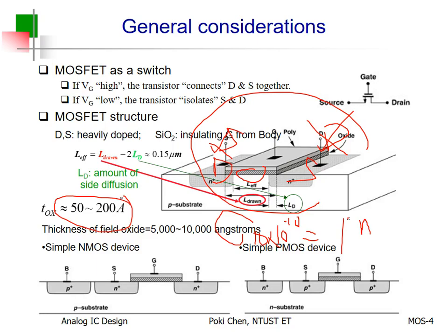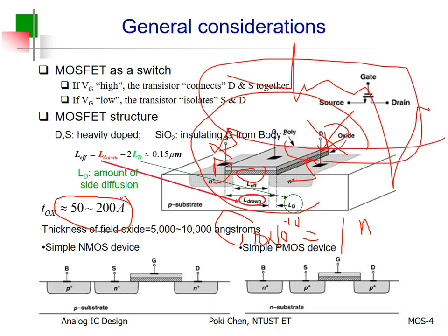Okay? Yeah. It is much easier to be penetrated by voltage ripple because everything is not perfect. Even for your VDD, even for your control signal to the gate, you don't expect a flat voltage. No, you have ripples, spikes.